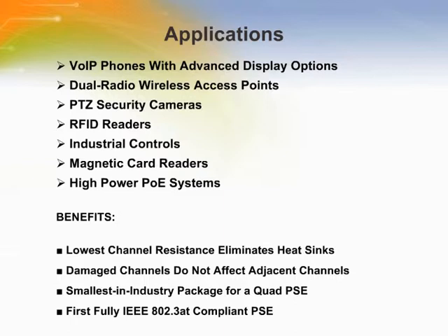At the heart of the LTC4268-1 is a high-performance switching regulator optimized for isolated power over Ethernet applications. The LTC4268-1 is designed to be a complete solution for power devices applications with power requirements up to 35 watts.